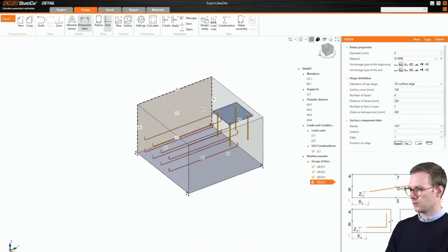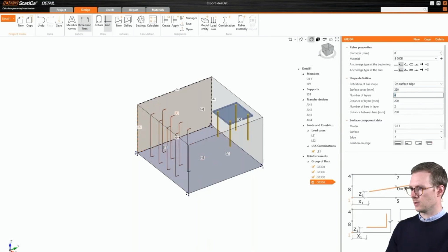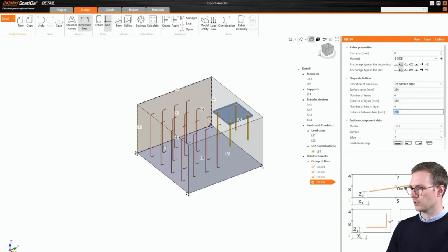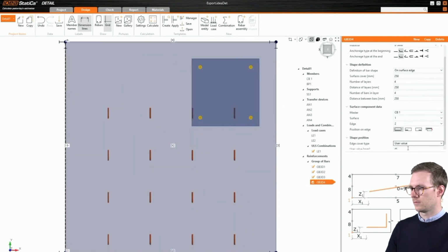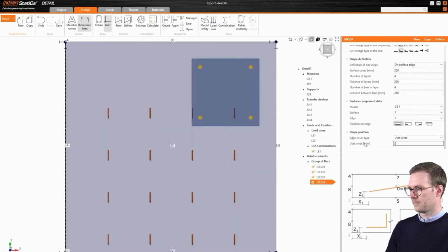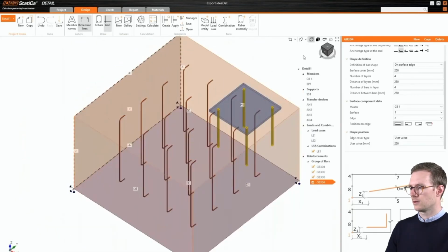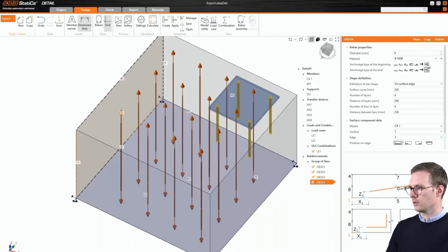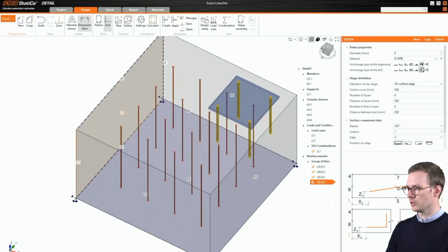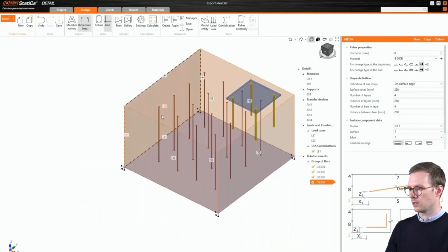And then, these will act as parts of the stirrups going through the middle of the concrete block. So we will distribute them evenly over the concrete block, like this. And now, lastly, we will define how these bars will be bonded. So we will define a perfect bond so that they will be a part of the stirrups.